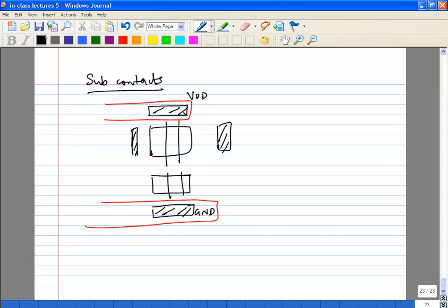Because you want to give a really good substrate. Remember that a lot of transistor parameters depend on the substrate, things like threshold voltage. If there is any substrate current, and there will always be some RF current being sent into the substrate, what you will see is that if the substrate has some series resistance, that will build up a voltage. And if your substrate voltage is wiggling, then your transistor threshold voltage is changing over time, for example. So you want to prevent that.